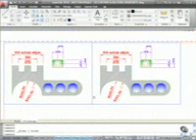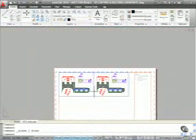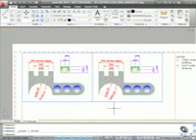What we're going to do now, now that I've copied a viewport, is look at this. I've got 2 viewports that are, in essence, exactly the same. Now you'll notice I've got a different color dimensions layer in one of the viewports. The reason I've done that, if you look at the dimensions, they're different sizes. That's to accommodate different scales in the viewports.